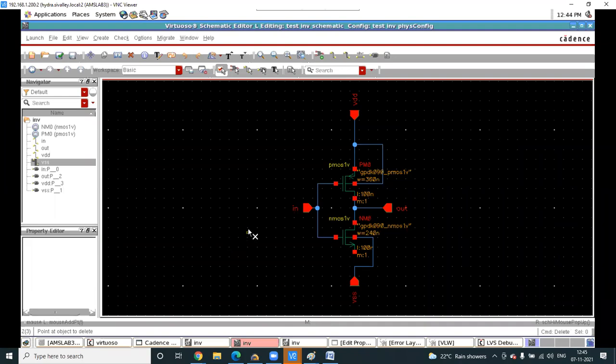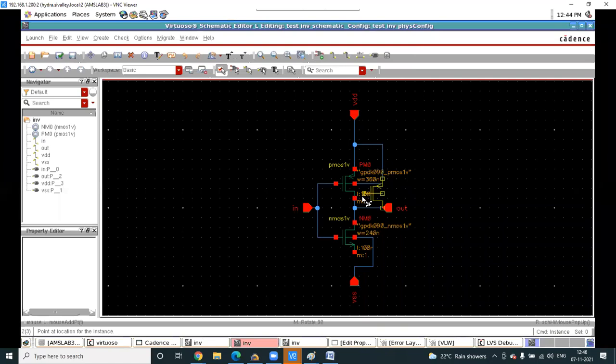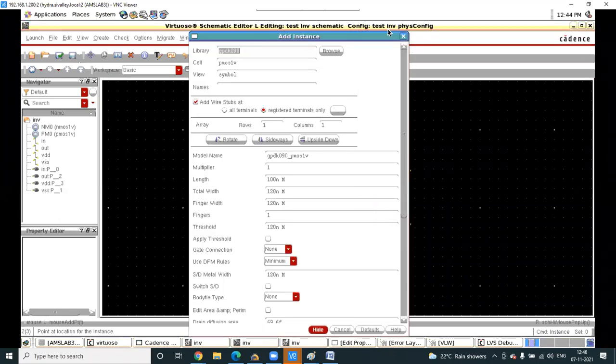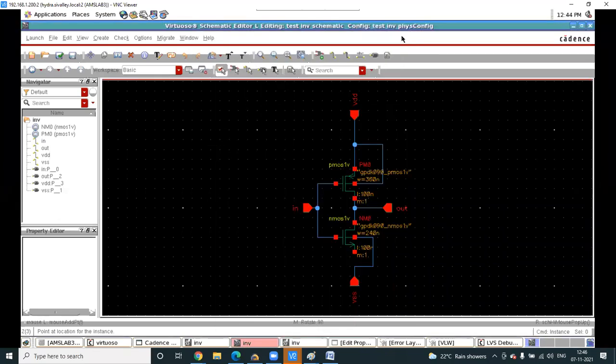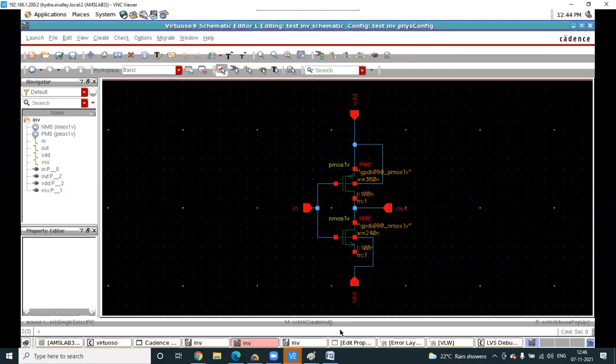In this device, we have connected this source to here. It is like this. Means in the layout we didn't connect this source to here. So in layout, it is not identifying these devices properly. Means some source is missing, so it will come under device error. But you don't need to clean device error first. It will come under net error. So first you clean net error, automatically device error will be clean. You're getting?